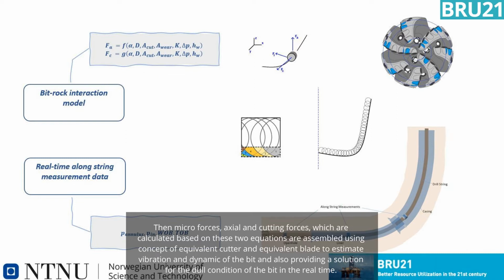Then micro forces, axial and cutting, which are calculated based on these two equations, are assembled using the concept of equivalent cutter and equivalent blade to estimate the vibration and the dynamic of the bit, and also to provide a solution of the dull condition of the bit in real time.